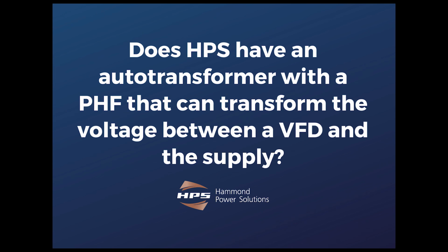For the most part, we don't offer that, and the reason is that we do offer passive harmonic filters in the most common VFD voltages in North America. By far, the most common ones are 480 and 600 volt. If you do need to transform the power, typically we would do that with possibly a drive isolation transformer before the passive filter, but not between the passive filter and the VFD.